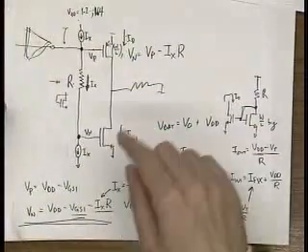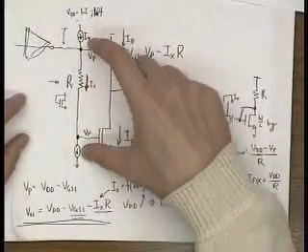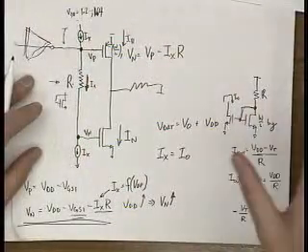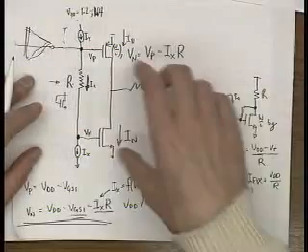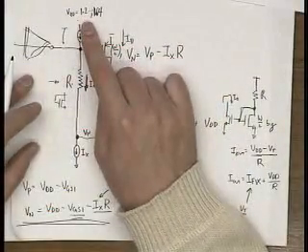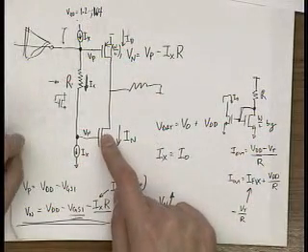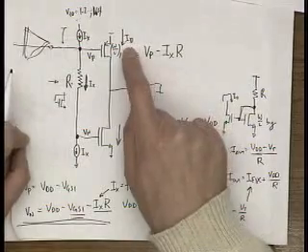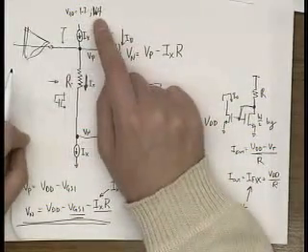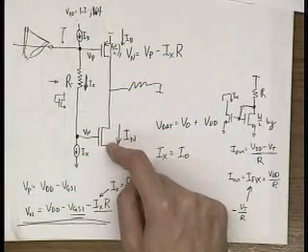Now let's assume that you design it such that at 1.2, and these currents are fixed, so you're not doing this hack or this tweak that I'm talking about over here. These currents are fixed. Let's assume that at VDD equals 1.2, you get it such that the NMOS device current is exactly spot on. It's exactly equal to ID. Okay? Therefore, at 1.4, this device current is going to be way off, right?